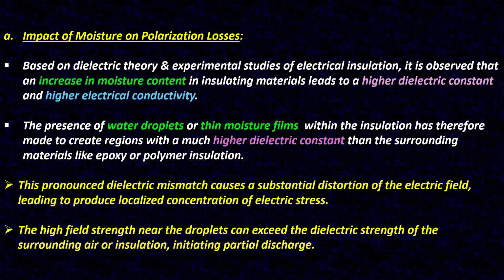Impact of moisture on polarization losses. Based on dielectric theory and experimental studies of electrical insulation, it is observed that an increase in moisture content in insulating materials leads to a higher dielectric constant and higher electrical conductivity.